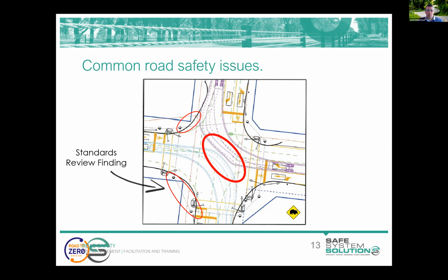A road safety auditor certainly wouldn't be expected to prepare any swept path diagrams. You would often receive them. If I didn't receive them, I would make a comment in an audit report to that effect, and that they should be reviewed. If I had any sort of big concerns with there not being enough space, I certainly would be requesting them from the designer. And as I say, if they're not forthcoming with that, that really does ring the alarm bells.